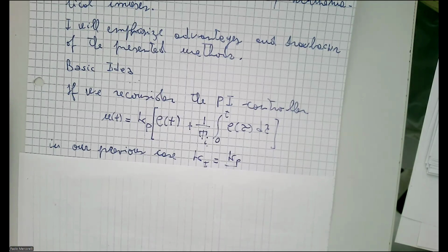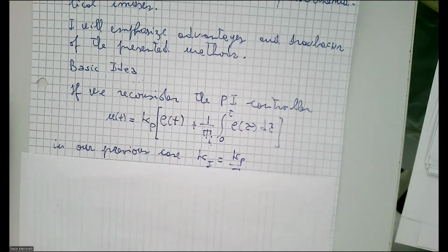This means the emulation method makes sense in the form that we achieve the goal using a continuous controller, which we are able to design, and then we discretize just the controller. I don't want to use the word direct because direct is used for another method. We emulate, in discrete form, what we obtain in continuous.